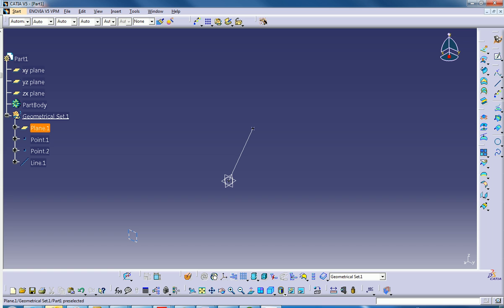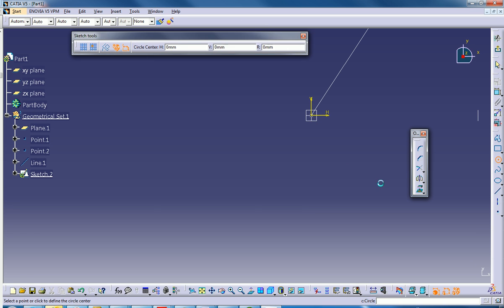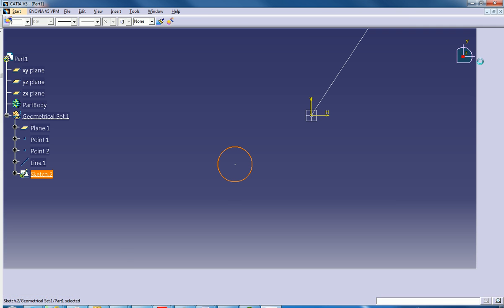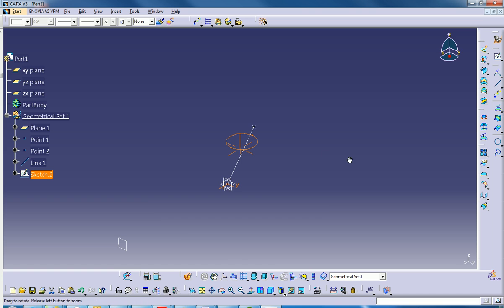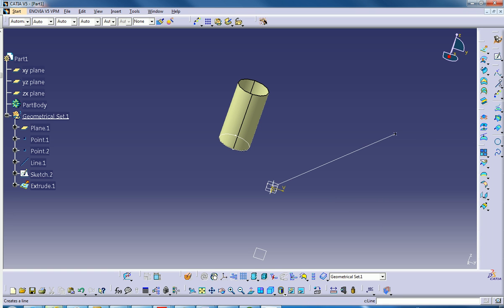Also, we can create what they call an axis. An axis is really useful in cases where, let's say, I have a sketched circle. If I quickly go ahead and create a cylinder now out of this simple circle, so say we extrude that, and we hit OK, you can see that I can now go into the line command.